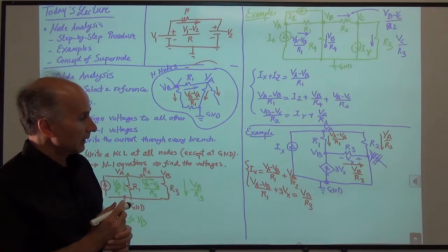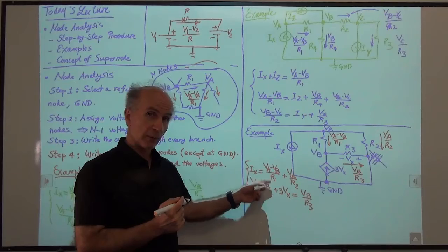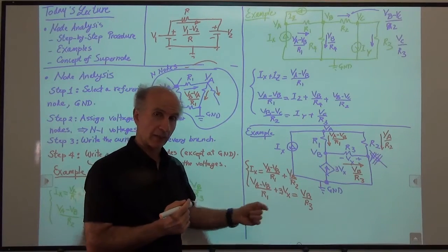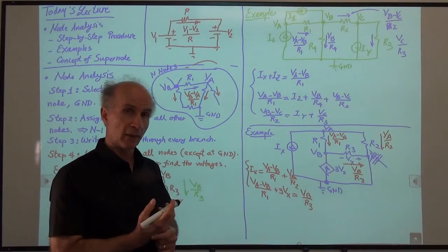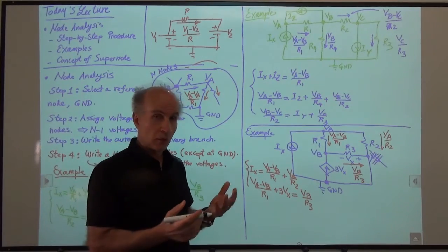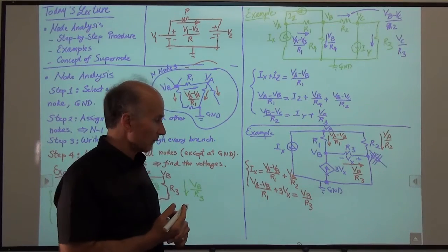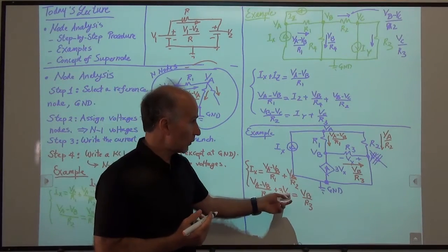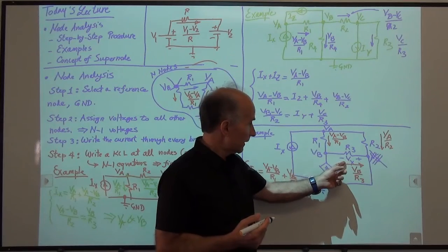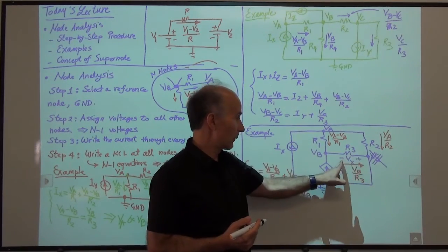Okay, that's great. The only issue is that we have two equations and three unknowns, because we have VA, we have VB, and we have Vx. So how do we handle that? Well, we have to look for another equation. We are done with KCL, so we have to look for some sort of KVL. Vx is a voltage, so let's go and see where Vx is. Vx is denoted as shown here, plus here, minus here.